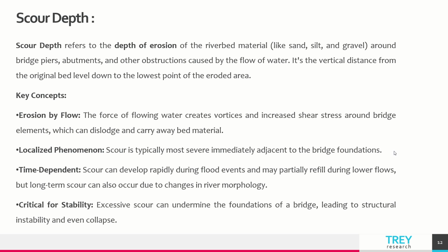Scour is a localized phenomenon and is typically most severe immediately adjacent to bridge foundations. Also, it is time dependent. Scour can develop rapidly during flood events and may partially refill during lower flows. But long-term scour can also occur due to changes in river morphology.